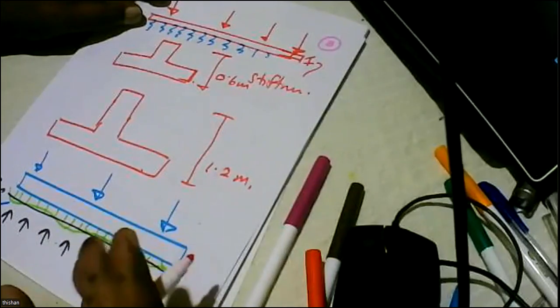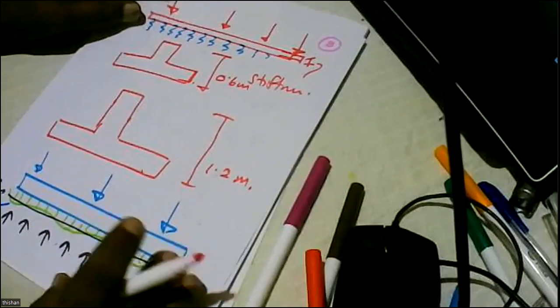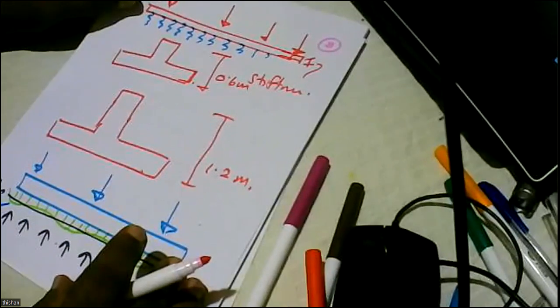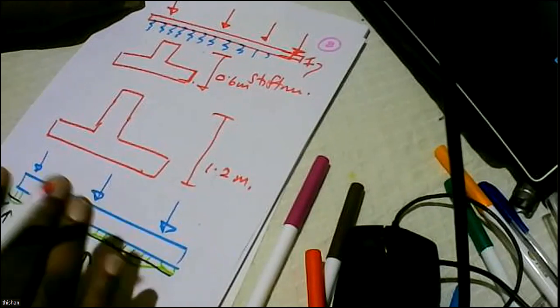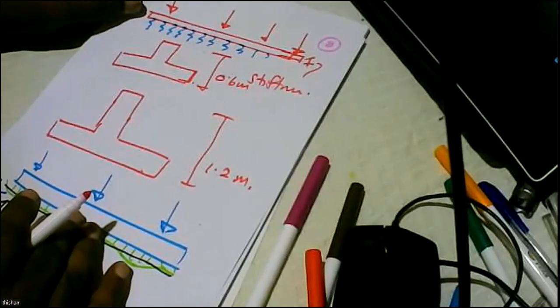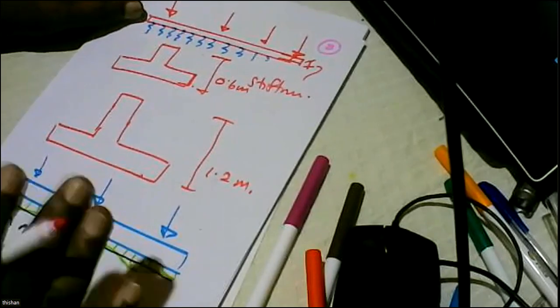You can rerun it, look at the results, and you can have a lot of interesting experiments before we select the actual parameters for the building or the bridge under consideration. So the Winkler spring method is fairly straightforward, but it's a very useful method. It may not be extremely accurate, but it gives a reasonable accuracy. So that is one way of looking at it.